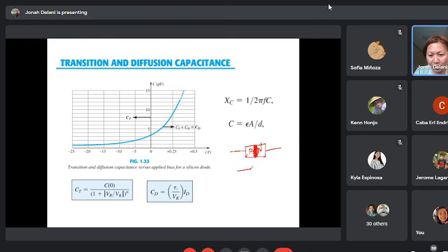If we approximate it, this can be modeled like a capacitor. The material between the capacitor plates is an insulator, a dielectric material, and a dielectric material does not allow current to flow. So it is like a capacitor. So a diode, when subjected to a very high frequency, would have a capacitance. At the reverse bias region, the capacitance that has a large value there is called the transition capacitance.